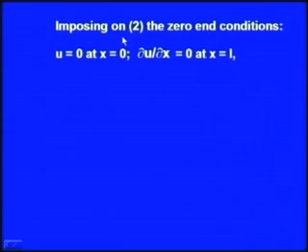So, now what we will do, as we have done in the case of finding temperature for a bar with non-zero end temperatures, is that we start with zero end conditions. That is, we assume that at x equal to 0, u is 0, which is given to us. At the end x equal to L, we first assume that the temperature gradient is also 0, and then we shall take the case where the gradient at the end x equal to L will be taken as A.